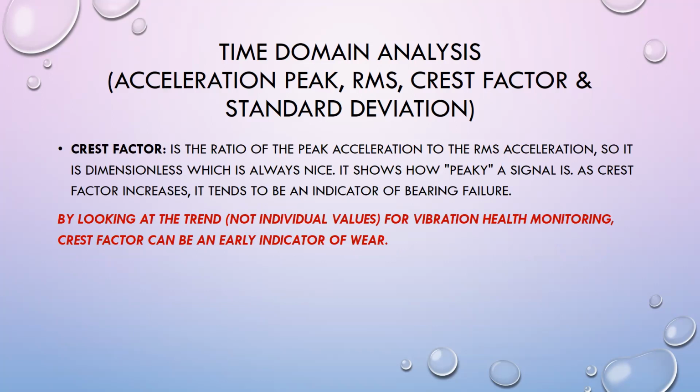Another parameter is the crest factor, which is the ratio of the peak acceleration to the RMS acceleration. In fact, it is a dimensionless parameter, and it shows how peaky your signal is, and you can study this parameter again for vibration health monitoring.